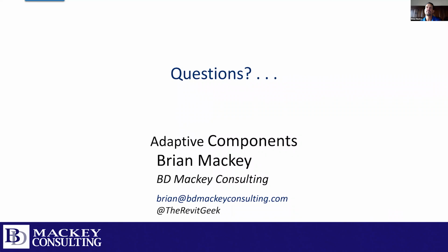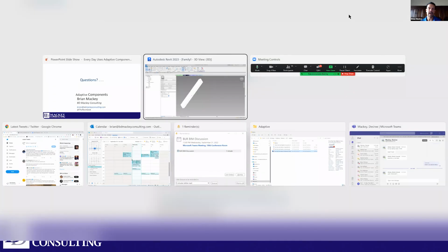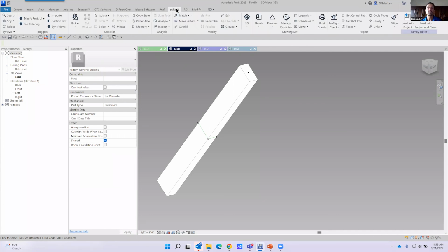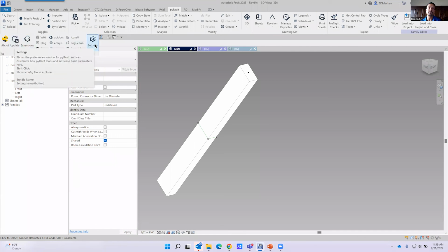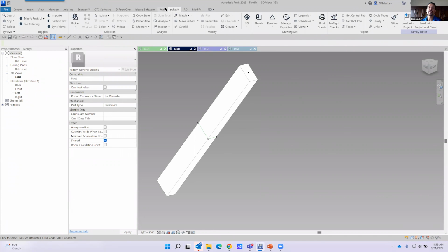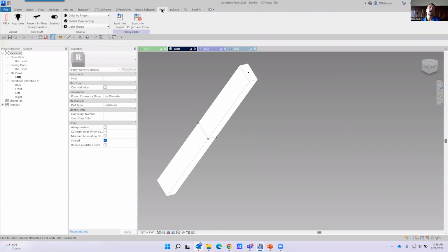And it looks like, yeah, I should have started with this. Somebody else asked, how did I get the fun color-coded tabs in my Revit? There are 2 add-in utilities to do it. If you're actually using PyRevit, which now is out for 23, if you guys did not know this, in the PyRevit drop down under settings, under UI, you can go through and set that up. I personally am not using that one. I am using the add-in that is a paid add-in from Parallax. It gives me view sorting and a few other options that PyRevit doesn't do, but you can use either of those, and that's how I get those color-coded tabs.